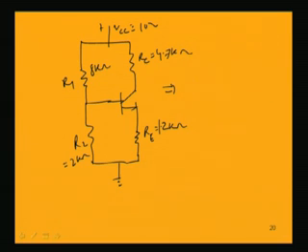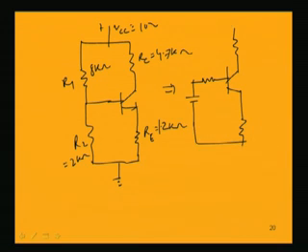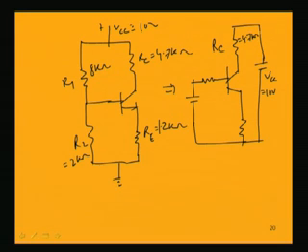So, now I can, approximately, first draw the equivalent circuit using Thevenin's. So, this whole circuit can be written down as the circuit using Thevenin's equivalent like this. So, you have VCC, which is 10 volt, RC is 4.7 kilo ohm, R Thevenin and V Thevenin we have to find out, and RE is given as 1.2 kilo ohm.